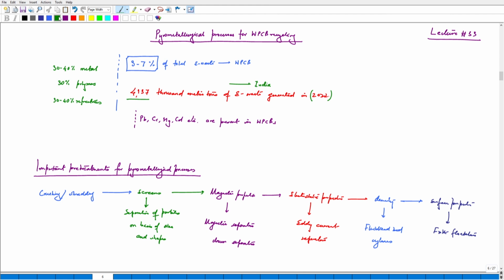We will generate lots of gases. The slag composition is going to be very complex because we are going to have many polymers and different materials coming into picture, and the product that we will get may not be of our desired composition. So removal of components and pre-treatment helps us to make the metal fraction more concentrated, more oriented. So the raw feed is of basically our own choice. We are able to design our raw feed for higher metal recovery.